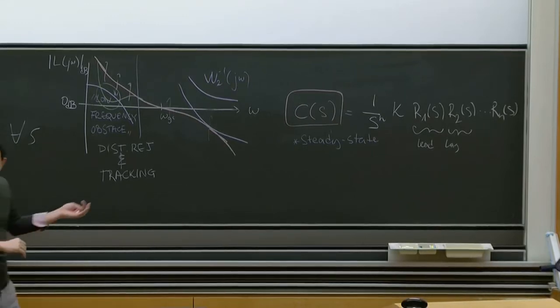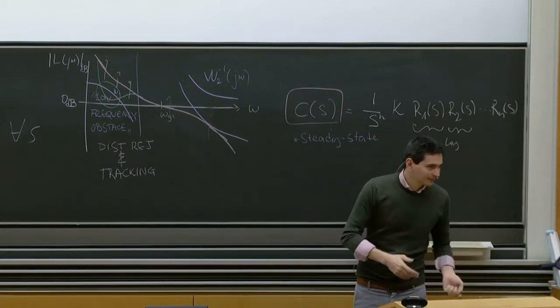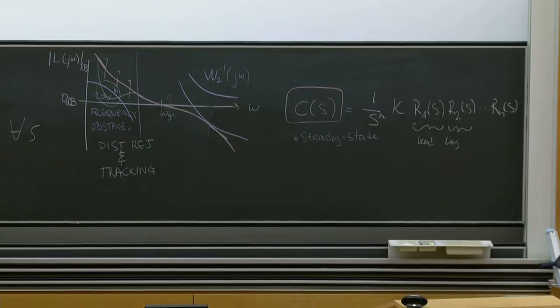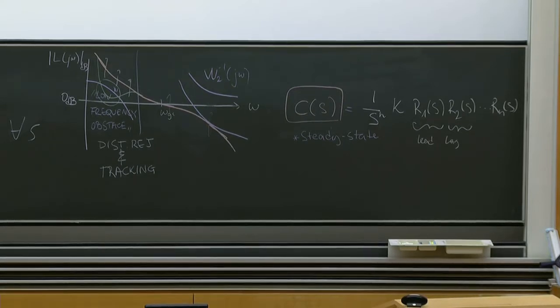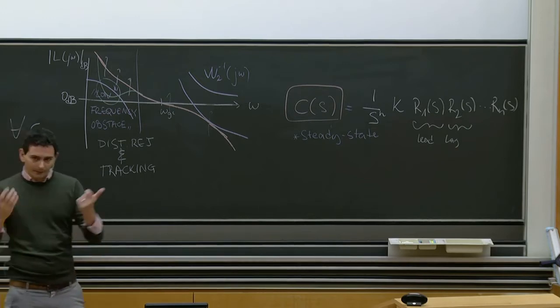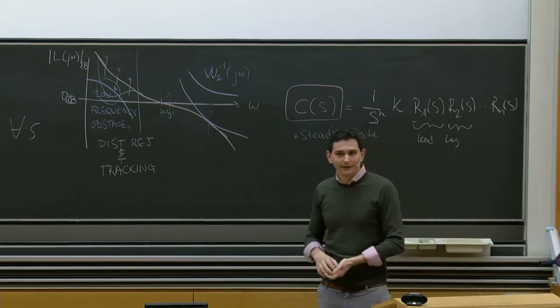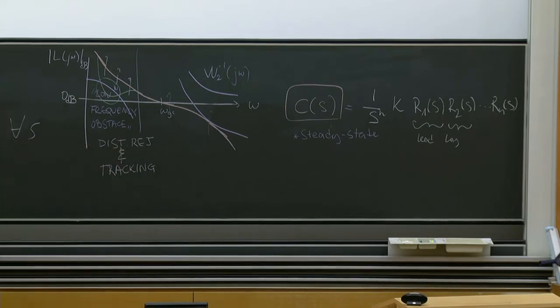But thank you for mentioning the PID. I'll do a small parenthesis on the PID. So we said that basically this loop shaping is the most powerful thing that you want to learn. Okay, this will work every time. For whatever system you have, even the ones that are really inherently complicated to control, the loop shaping approach is the one that will make you meet your specifications. But PID is a very commonly used controller, and it's really, really famous. It's used in practice a lot. If you have to try something quickly, if you want to control a system, the first thing you do is PID. It's like the no-brainer. And this is because it's effective, it's super easy to tune.